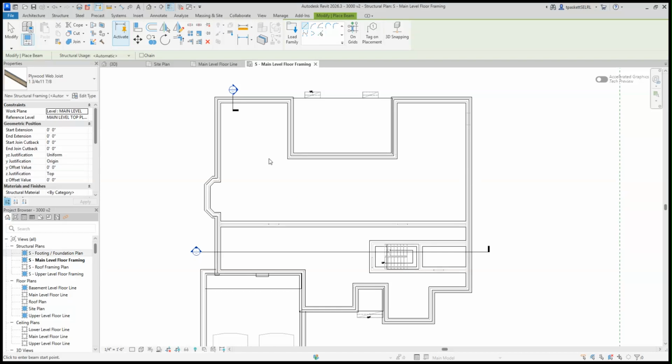We have our live load and dead load. The minimum here is what is the code requirement. If you exceed the code requirement, then that means you got extra built into the design of this truss and the joist to make it last longer. And you'll hear me use truss and joist a little back and forth on these. There are floor trusses and there are floor joists. A truss is open webbed, meaning it has a lot more holes through there like a truss would have.